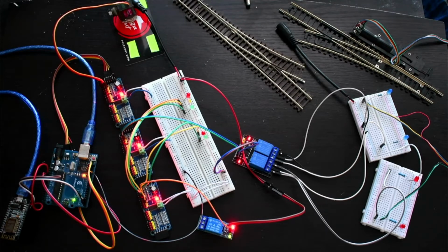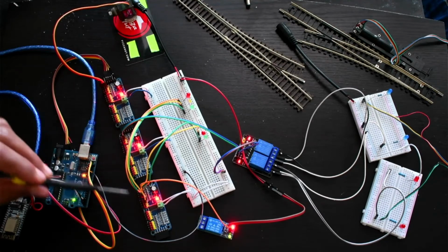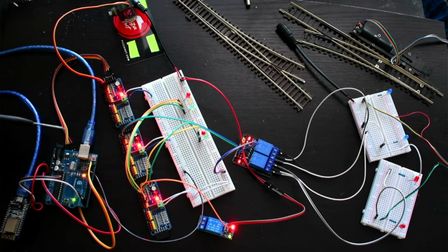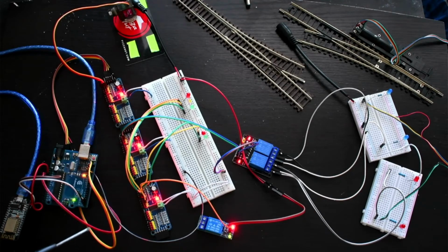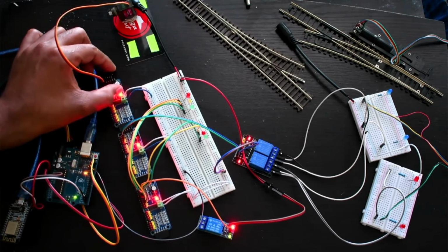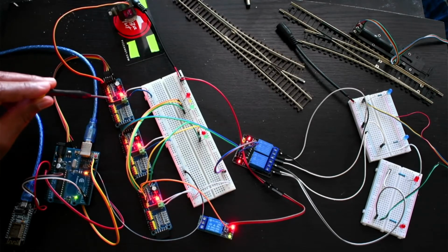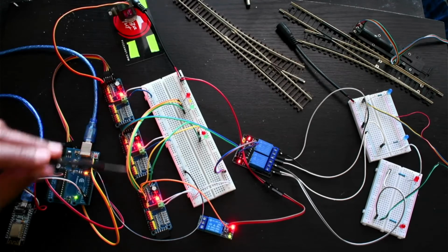And then next we will see, here we have 3 boards, board number 40, board number 41, board number 42. Here you can see it is connected via the Arduino Uno. This yellow and orange are the SCL and SDA lines, serial clock and serial data line, and this red and brown are the 5-volt power supply and GND, which go to the first board here. From the first board, all 3 boards are chained.